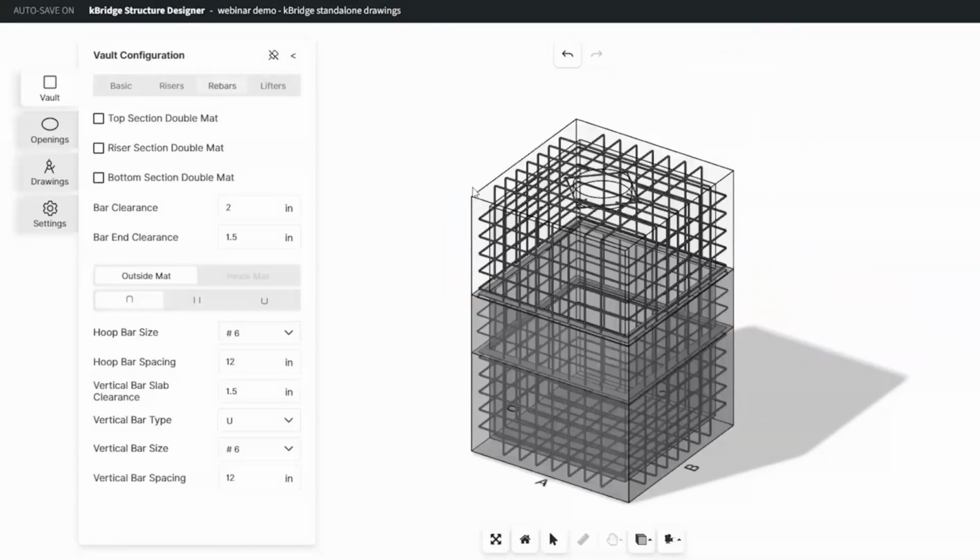And then you'll notice here in this view, we're looking at the rebar in the model view. And again, this is important to understand the thickness of the concrete, the amount of rebar to handle this is going to be submerged, underground to house a pump or other pieces of equipment. So it needs to be structurally sound to make sure it doesn't implode just from the weight of whatever the fill or the soil is and so on.